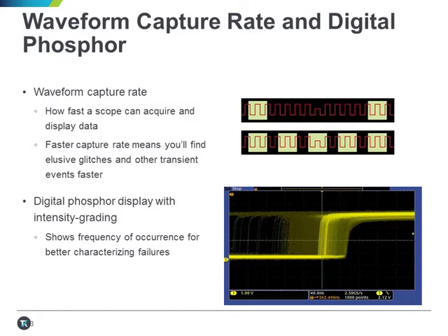You can also imagine that if I had a much faster camera, I probably would have a better chance at catching the blinking. This is illustrated with the upper graphic on the slide, as we try unsuccessfully to capture an infrequent runt pulse on an oscilloscope that has a slow waveform capture rate, and successfully on a scope that has a much faster rate.